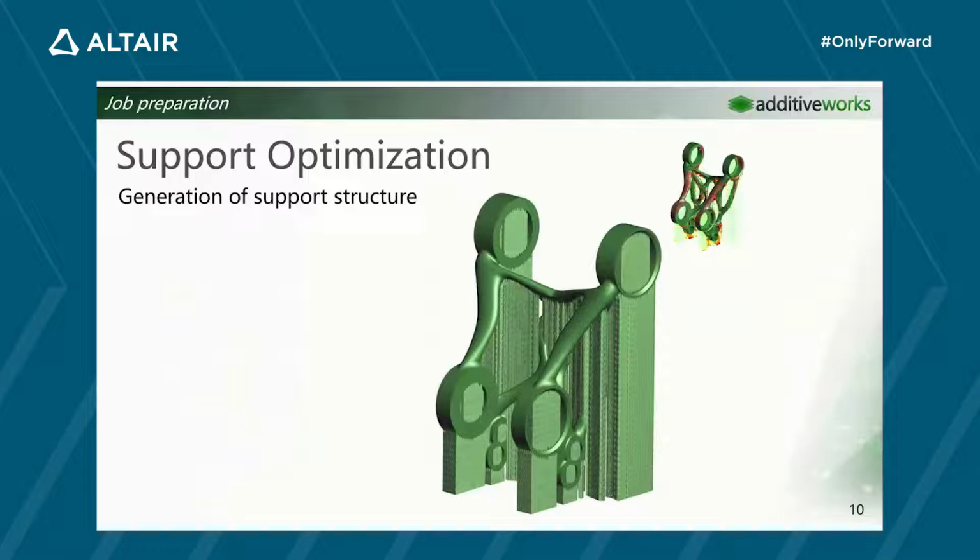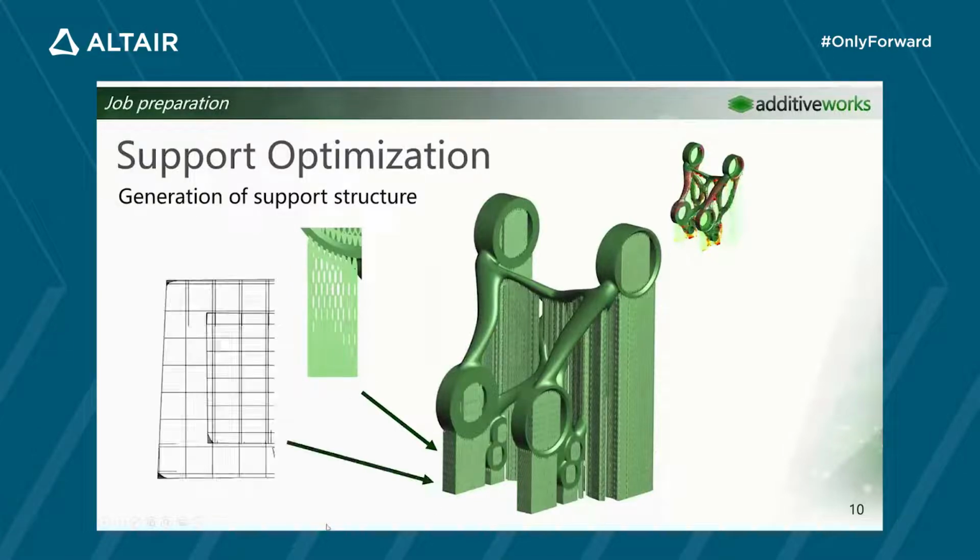The generated supports look like that. So as mentioned, 2D block support structures, but now we can check that there's a difference and a grading, for example of the perforation, like here. If you see the small image above, there's some higher density close to the base plate, and we can see that the perforation is more and more closing.